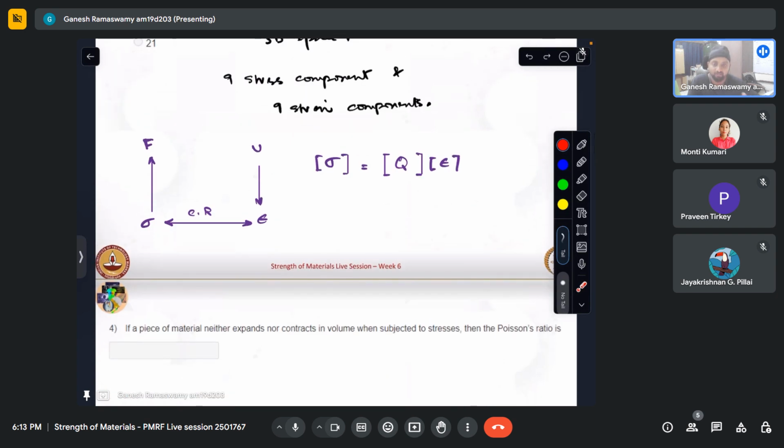But from our knowledge of symmetry of stress tensors, symmetry of strain tensors, and other strain energy considerations from continuum mechanics, we will see that such a matrix, where there are essentially 9 rows, will have many components that are not independent of each other. So it will go to 0. That is how from 81 we come to 54, then 36, then 21. That delves more into continuum mechanics. I won't get much into that.